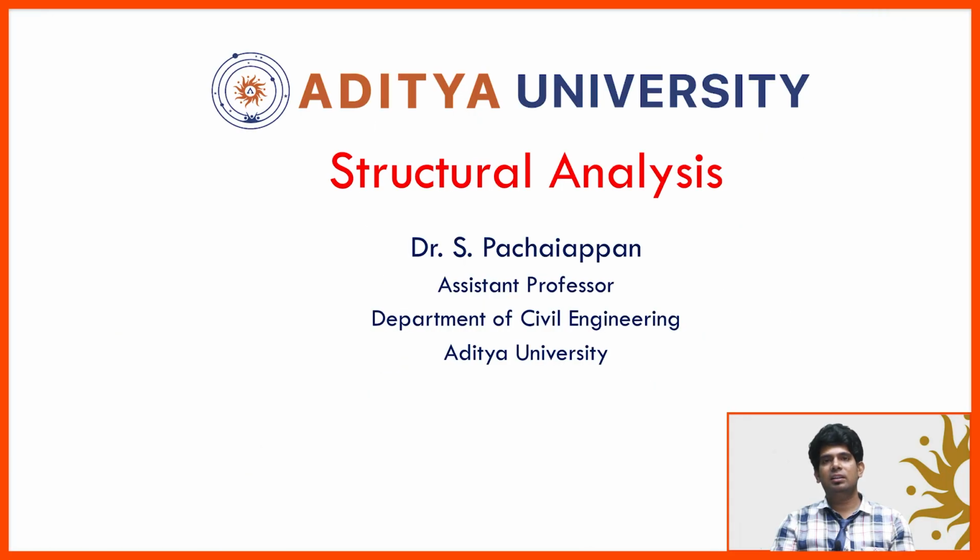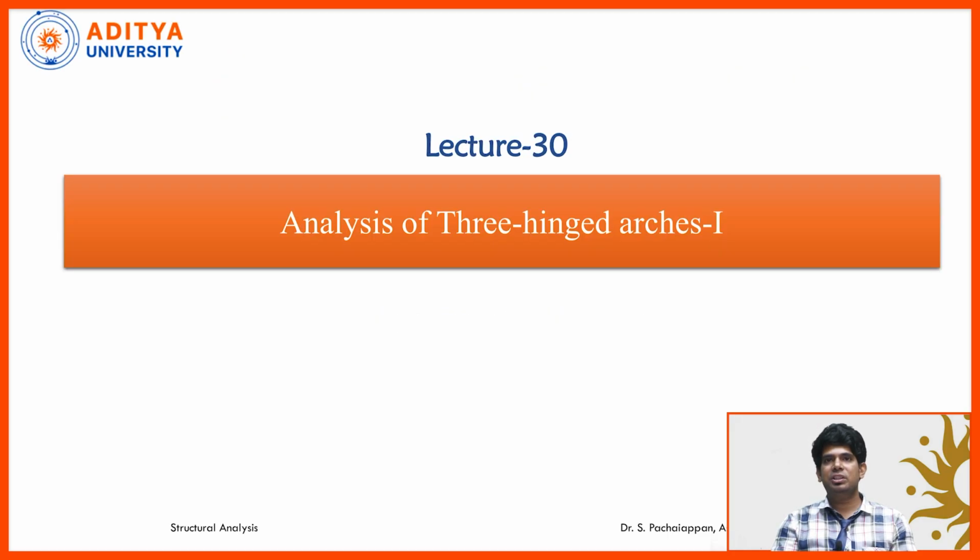So today we are at the 30th lecture and we are going to discuss analysis of 3 hinged arches. So far we have discussed analysis of 2 hinged arches, which is a statically indeterminate structure. But the analysis of 3 hinged arches is a statically determinate structure. That is the main difference. Problem solving for 2 hinged arches is tedious and consumes a lot of time. But in the case of 3 hinged arches, the time taken to calculate the horizontal thrust is comparatively less. So lecture 30 is the first lecture on analysis of 3 hinged arches.